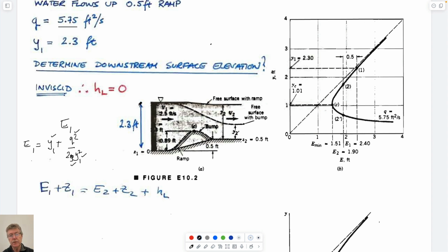And since we're at 2.3 feet, the depth of this is here. So this is the point that we'd be on this curve upstream. If we go through a change in depth between this top and this top to a depth of only 1.01 feet, which is the location of this nose, then this forces the flow to go through this depth.